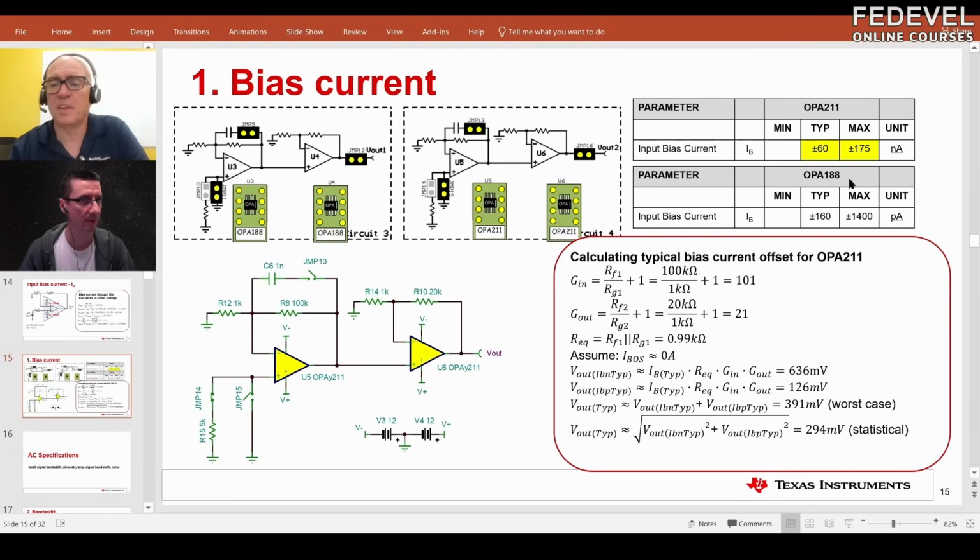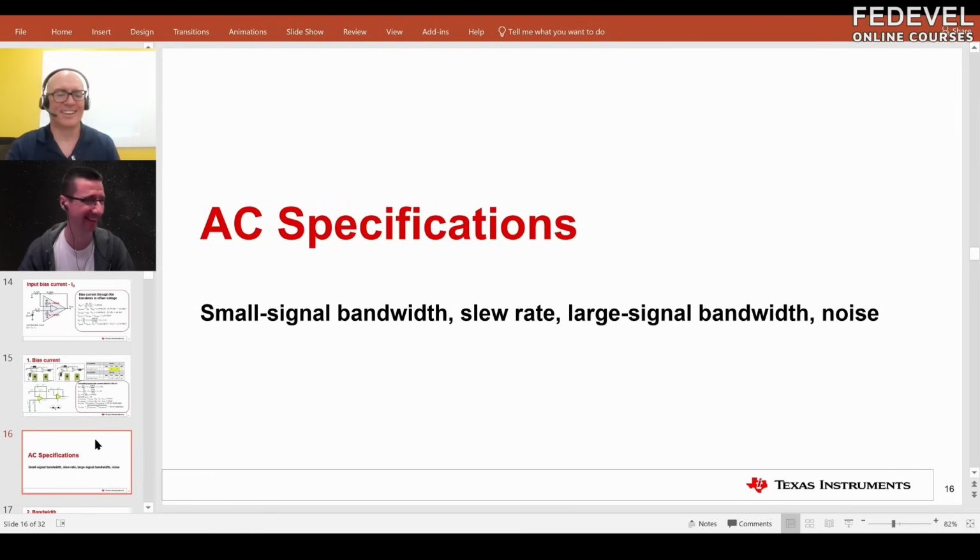And so this part at the top, the OPA 211, is optimized for low noise and good AC, low distortion, and so forth. And its DC performance is really quite good. It's exceptional. But this one at the bottom is what is called a zero drift amplifier, and it has an internal calibration circuit that calibrates off the offset. So it has an extremely low offset, these zero drift type devices. Huh. Okay. I just keep learning. Yes.